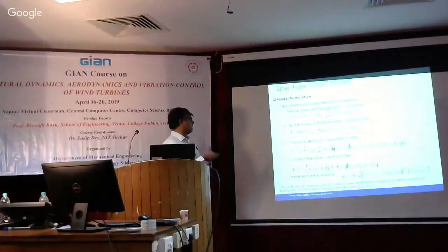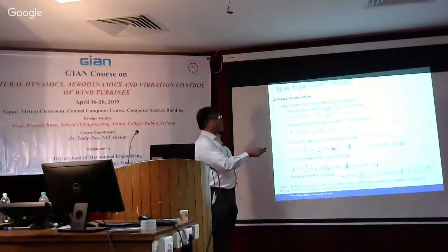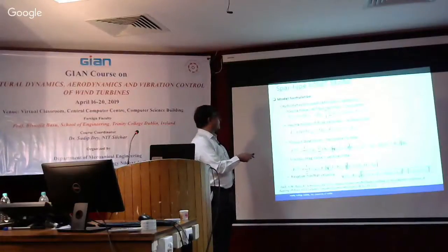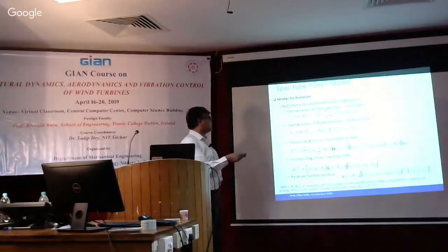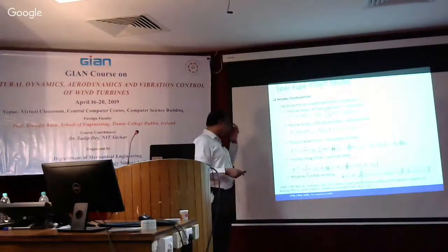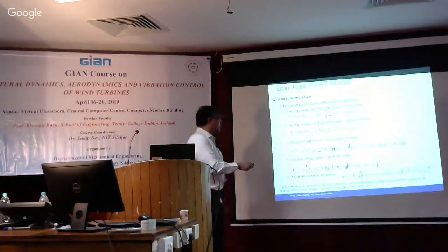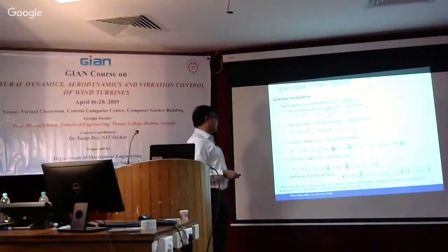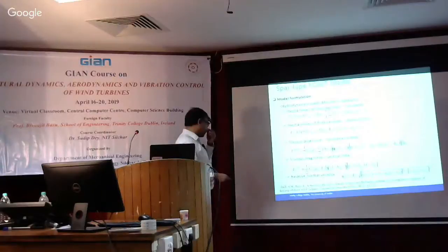And finally, this is actually a summary of all the loads we have, the hydrodynamic Morrison load, inertial force from the fluid particles. You can see it's proportional to the acceleration term here. The inertial forces from the fluid particle, you get the acceleration term here. The viscous drag forces, that gives you the square term, you see Q dot, and then you have this Q and Q_G. So this Q is the generalized coordinate. So a projection of this on Q_n will give you the square term, so it's the drag force. And similarly, you have also the vertical drag force as well. And then our net normal velocity given by this expression here.